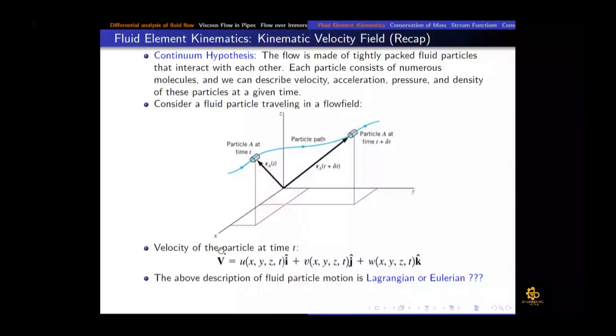in the Eulerian approach, we also need to know the coordinates at which there is information of that property. For the Lagrangian approach, it is only a function of time, because we are moving with that particle. So we don't need to know the location of that particle, only at which time instant we are recording that property. And velocity magnitude, we know that we take the squares, add them, and then take the square root. So that is the velocity magnitude, a very simple thing.